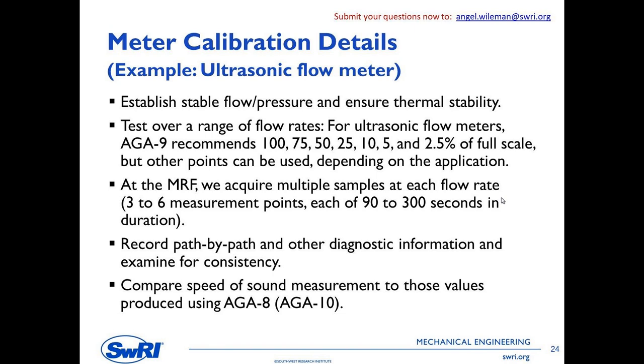It helps establish a baseline for the meter that you can use first when you install it in the field to make sure that the meter's still behaving as it did in the lab. And then it also forms a reference for you for later on. So when you come back 3 months, 6 months, a year later, you have diagnostic information to compare to. How is that meter performing? Is it still doing what it did when I first installed it? If it's not, well, then there's probably something you need to check.